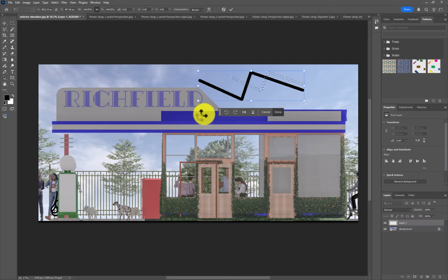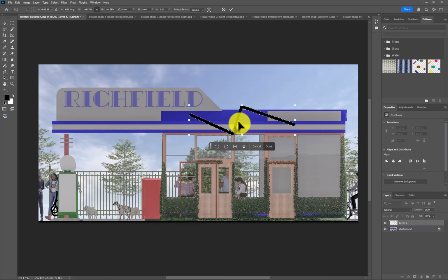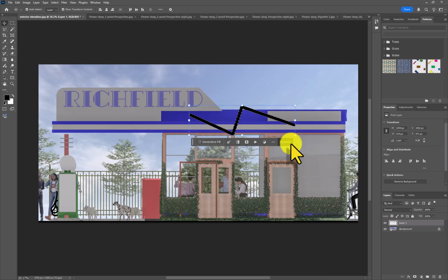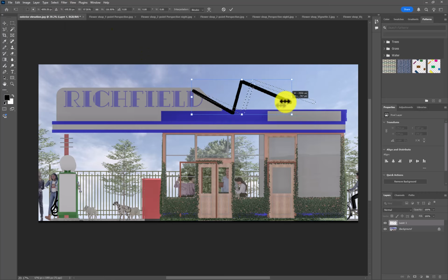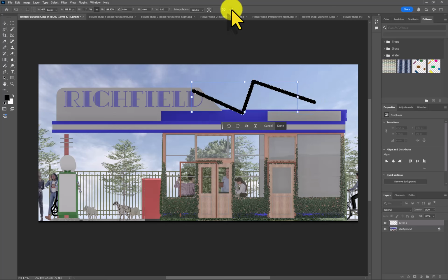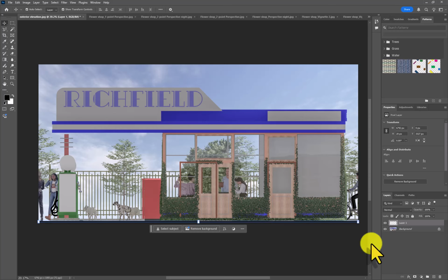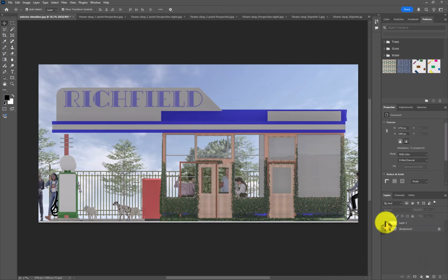I can manipulate it, and this is easy if you're having trouble seeing the very bottom of your elevation, or you're not sure and you want to kind of nudge it up and down. You can just use the arrow keys. Lastly, you can just hit delete and it goes away. If you don't see the transformation controls, by the way, sometimes I think by default they're not visible. Just select it using the selection tools as mentioned, but click this transform tools button and you'll see these little boxes. And there's all sorts of modifiers, holding down shift and that sort of thing. Anyway, I'll click the checkbox. I'll hit delete because I don't want that. And you can see it looks so much better with that nice dark line down on the ground.